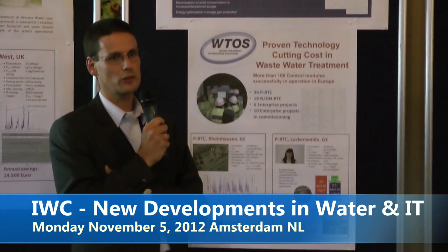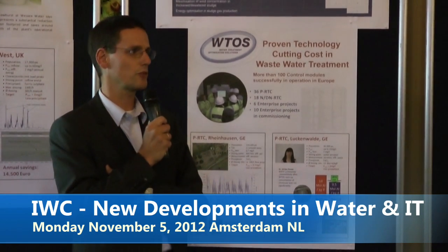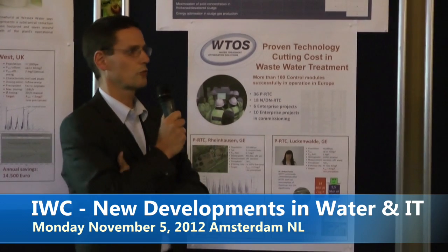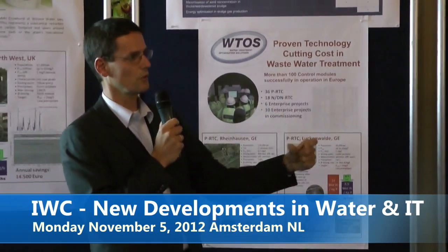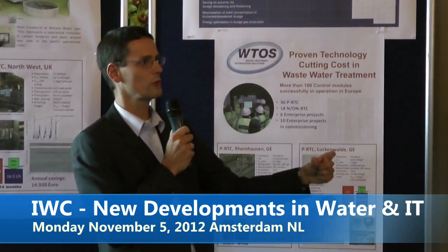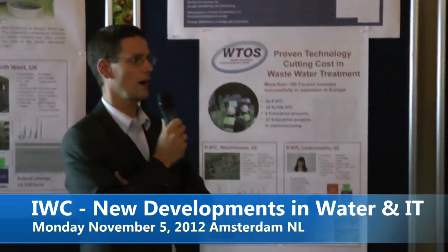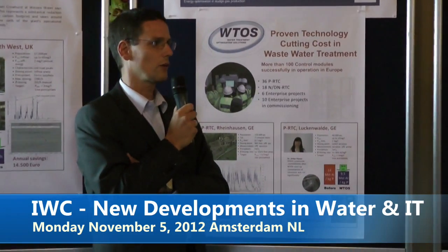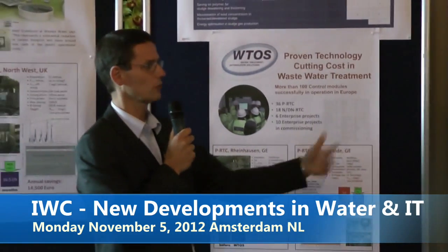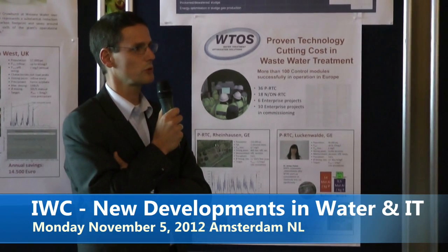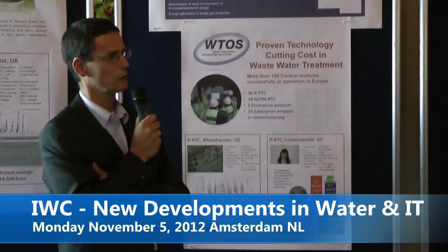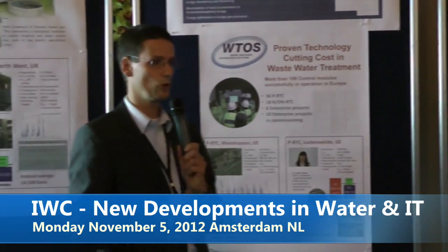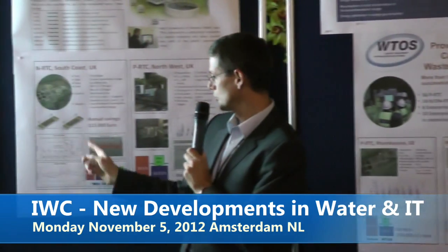The standard process applied by Southern Water is to have a DO concentration in each of the 4 zones: 2 milligrams per liter in the first zone, 2 in the second, 1 milligram per liter in the third zone, and 0.5 in the last zone. And we had the chance to add our NRTC to the other 4 lanes, so the other 120,000 PE which were treated there, and we could directly compare the results of our controller against that standard control of Southern Water. And the results are shown here.